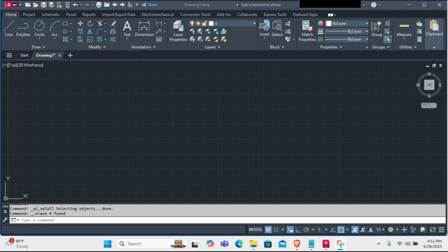Today's session is all about line control, that is cleaning up and connecting your schematic like a pro. We will focus on two incredibly useful tools, trim and extend. Trim is basically used for removing extra parts of the lines or wires, whereas extend is used for snapping lines exactly where they should go. So, by the end of this lesson, you will not only know how to trim and extend lines, but also how to switch between them with a single shortcut.